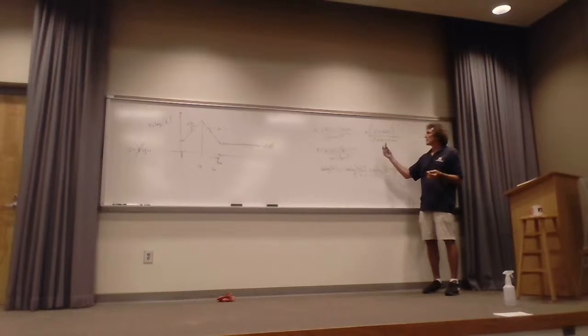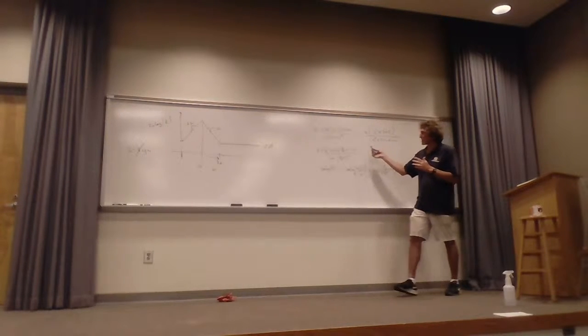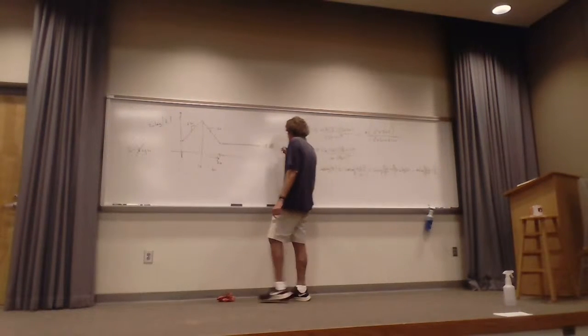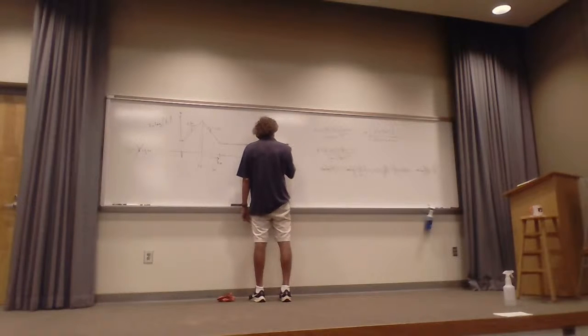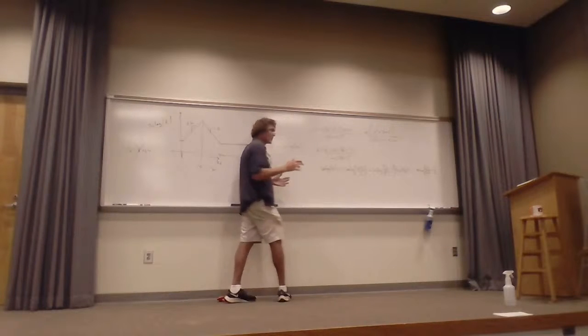As S gets very large, the S squareds dominate, right? And that means as S gets very large, if I'm plotting this thing, these two cancel, and I get the log of K. So right here, you can put down 25 dB is equal to 20 times log of K. Does everybody follow me what I'm doing?